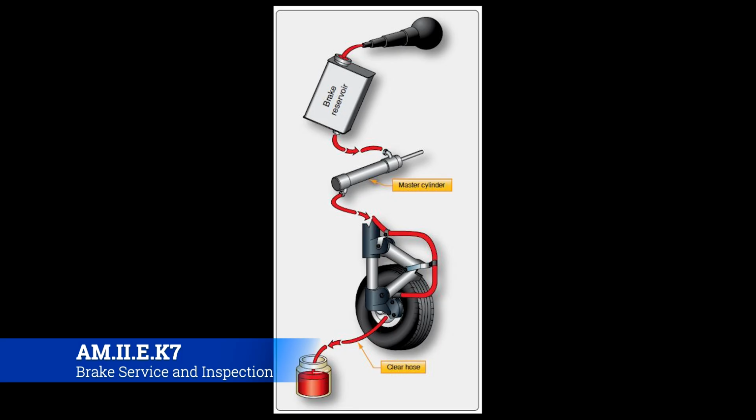So if air gets in there and it starts to compress and feel soft, you know you have a problem. Now, this is a method of bleeding the brakes. Bleeding basically means that you're going to pull the fluid out with the air, and replace that air with fluid all the way in the lines. Typically, the way I've always done it, you would press on the brake pedals. You'd have somebody up in the cockpit working it back and forth, back and forth, and you crack the little zerk fitting on there, and it'll let the air out.